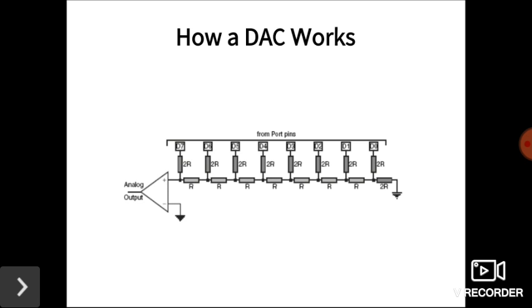In general, 2R is replaced by a value of 1M and R is calculated accordingly. The conversion time of this type of DAC is very short, generally a few nanoseconds. In general, metal film resistors, not carbon, are used for the R-2R ladder for the desired accuracy.